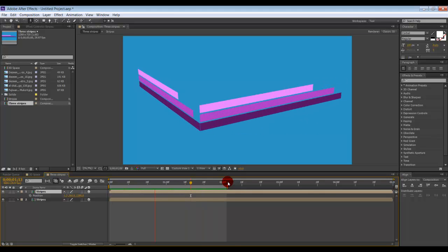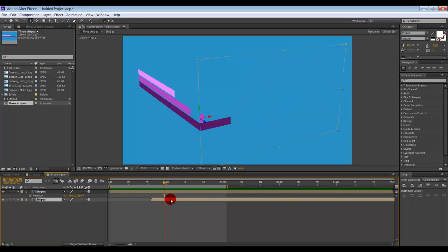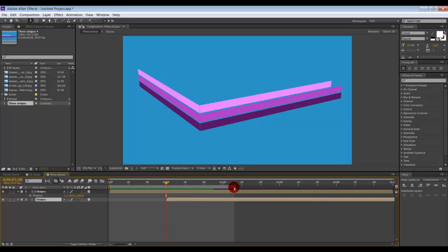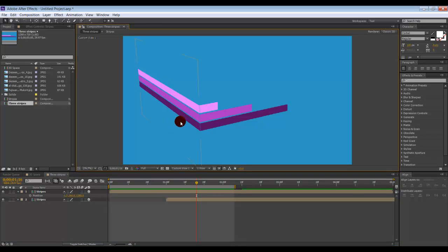Alright, what we want to do though is to have the second piece of animation start right after our first strip finishes this movement. So this frame here. So we can simply drag the timeline. And in order to make sure that we are touching the keyframe here, we can hold shift. So now we are perfectly touching the timeline, which seems to be here. Press 0 and see. Very good. They are not actually touching very well each other. That bothers me. Let's try to fix that quickly.